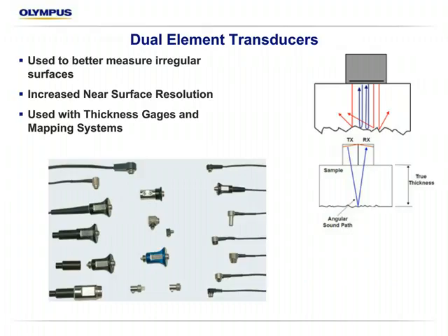The reason we tend to use those in a corrosion survey, especially for general wall loss and pitted back walls, is if we just use a conventional ultrasonic 0-degree transducer, we send sound into the part at 0, and because of this irregular surface, it'll often be misdirected, and the transducer will never see the response. By using a dual element transducer, we actually send with the send receiver and receive with the receiver, and these are set at a roof angle designed for varying thicknesses, and that gives us a better chance of hitting an irregular surface and getting the sound back properly to the receiver.